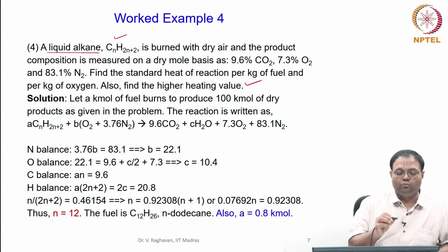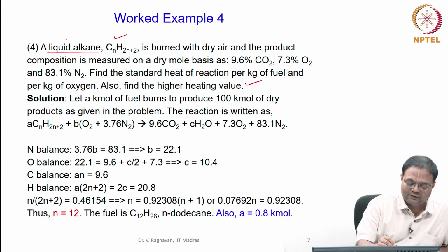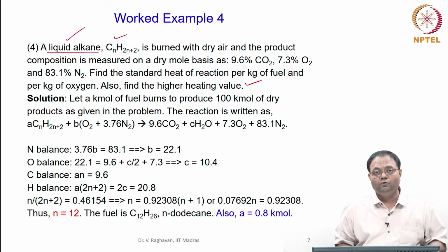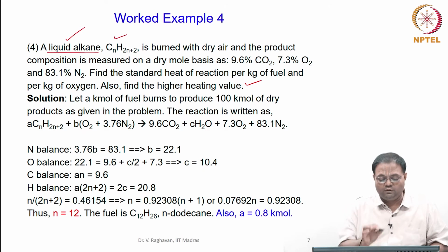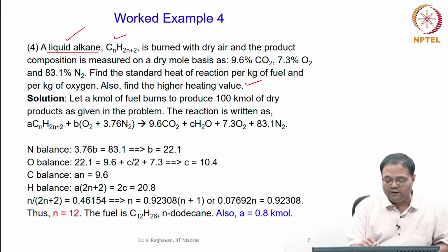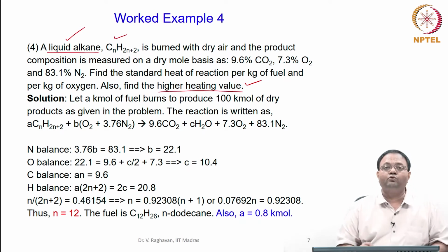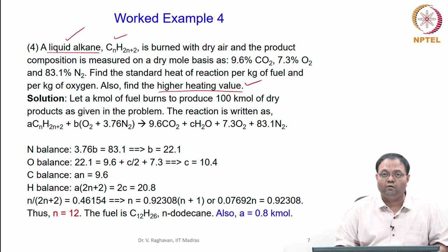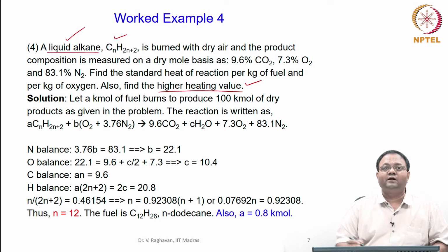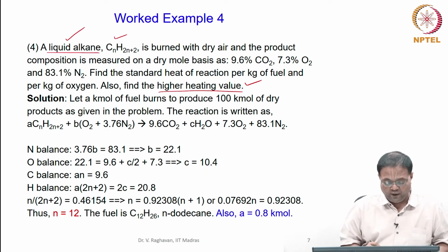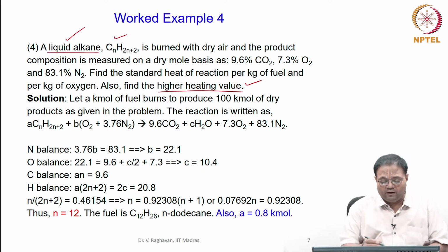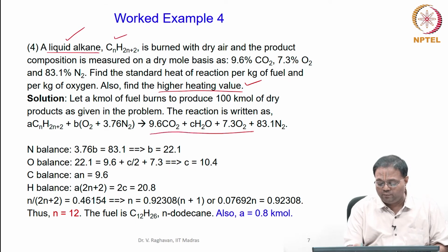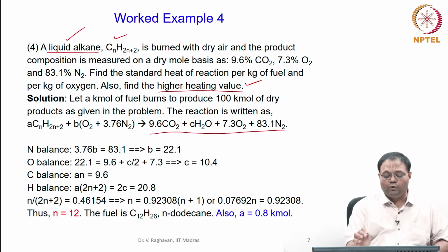Okay. Now you have to importantly understand that this is a liquid fuel. So the appropriate value of heat of formation, the enthalpy of formation, should be used. That is the only thing you should understand. Similarly, when I talk about the higher heating value, I should use the enthalpy of formation of water as that of the liquid in the products. Okay.